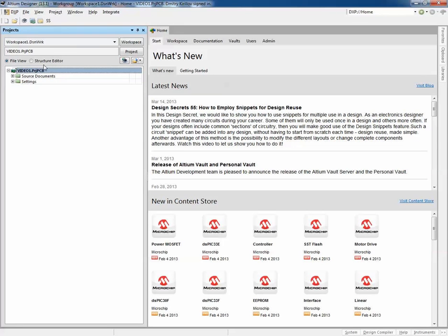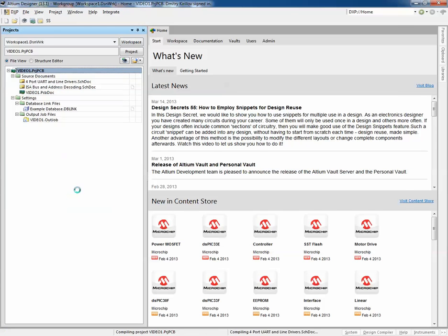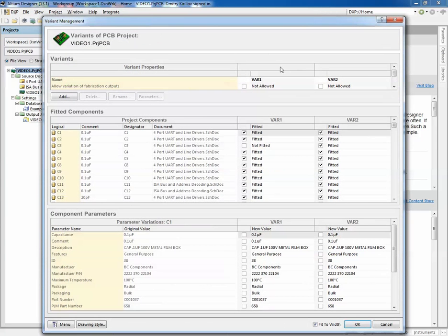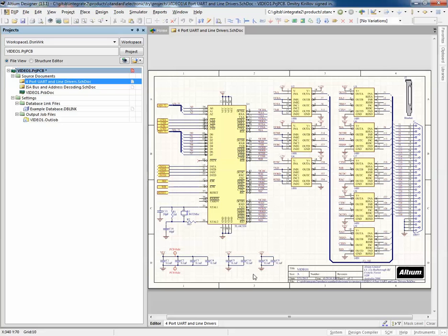As previously mentioned, for our demo, our template has some design and manufacturing data already included. So let's see what we have as a starting point for our new design. Here in Altium, for the design, we select Variants. And here we see in the variant window that we have 2 assembly variants with slightly different component sets. We have some schematic data with a drawing frame.